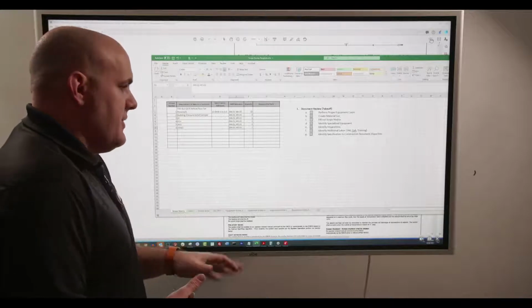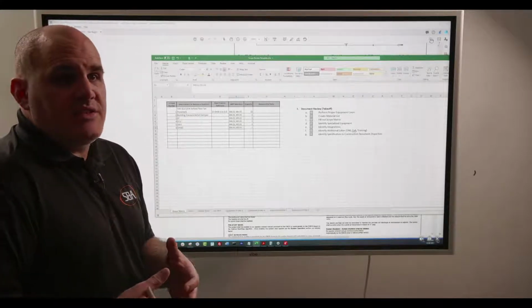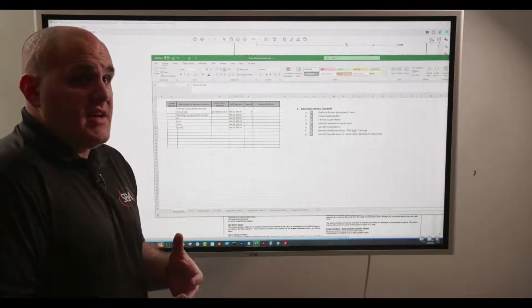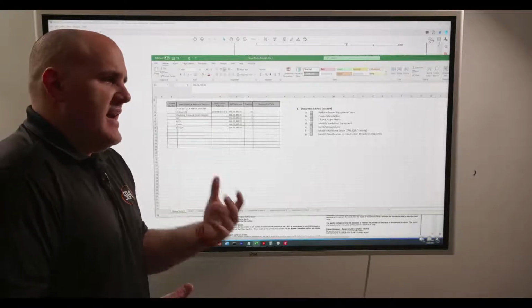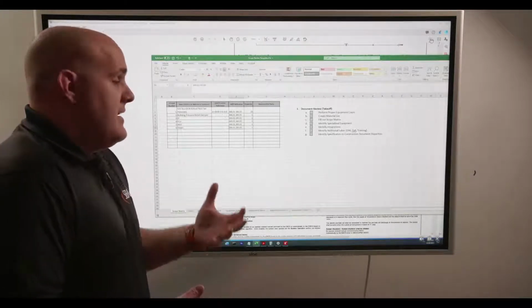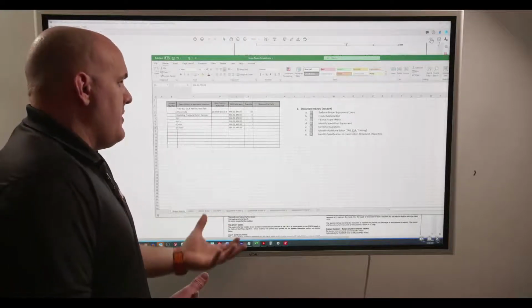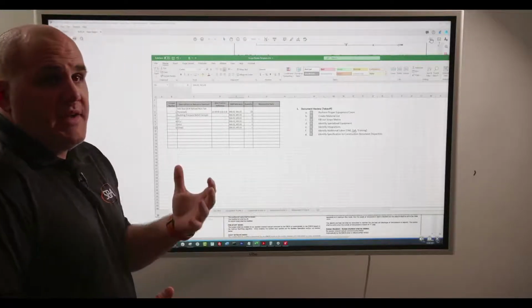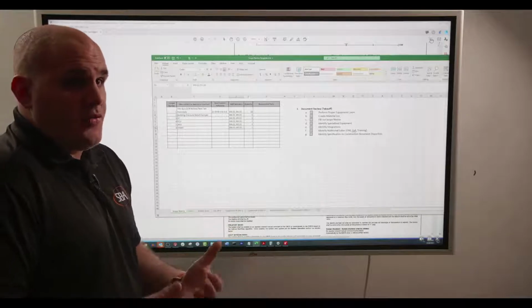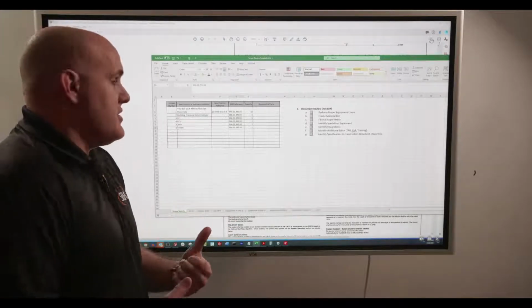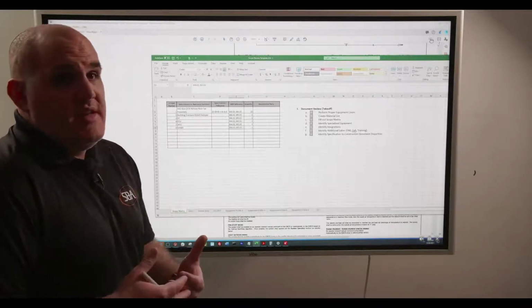You get the documents. You've got to make sure that these are CD phase documents. You don't want to be doing this off of SDs or DDs because the design is likely to change. So you want to be working off of CDs, and those are construction documents, right? Those are right before you actually execute construction, so the likelihood of those changing isn't as high.